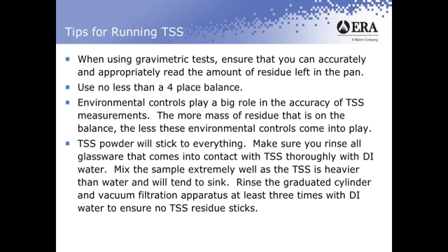You're also going to have TSS that's going to stick to the vacuum filtration apparatus. So once you've poured your sample and you've rinsed out your graduated cylinder, take your DI bottle and also rinse out the vacuum filtration apparatus to make sure that none of the TSS residue is sticking to that.